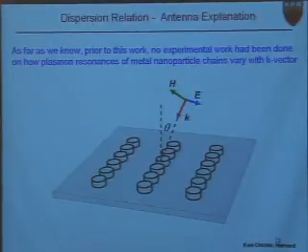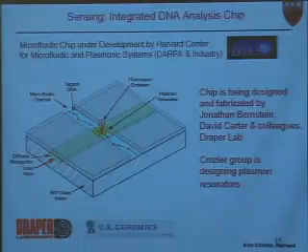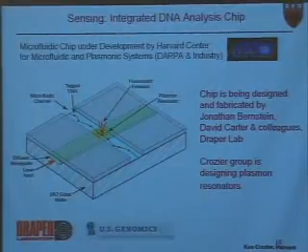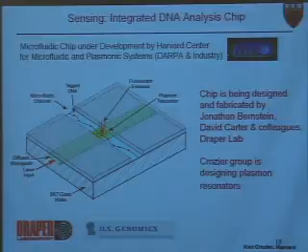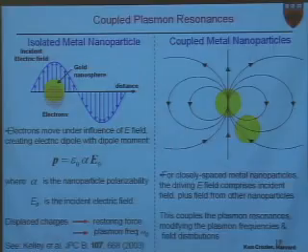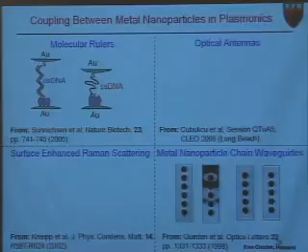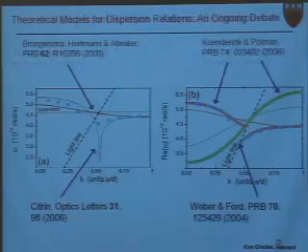Now, this is a very important problem to us because in our design of this chip, we have a K vector inside the waveguide. We've got to match it to the K vector along the plasmon resonance structure. Otherwise, we're not going to couple to that resonance where we get these greatly enhanced fields that we're going to be using for fluorescence excitation. And it's also important in metal nanoparticle chain waveguides to look at the matching and group velocity and so forth.